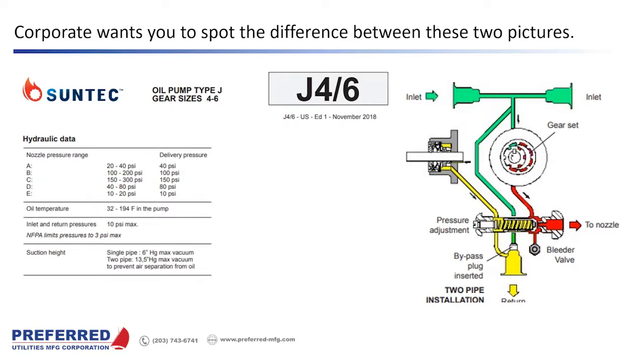And it shows a delivery pressure of up to 300 PSI. And then inlet and return pressures are no more than 10 PSI max. And check out that note. NFPA limits pressure to 3 PSI max. So Suntech doesn't understand the boiler market either.